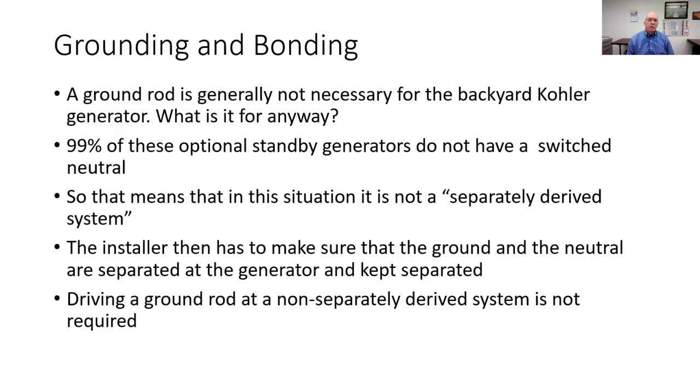I do not recommend, nor does the National Electrical Code allow you to backfeed a portable generator into a regular receptacle or a 30 amp dryer receptacle. You don't do it, because to do that you've got to make a cord with two male ends, and you're only asking for trouble. It's a dangerous situation.